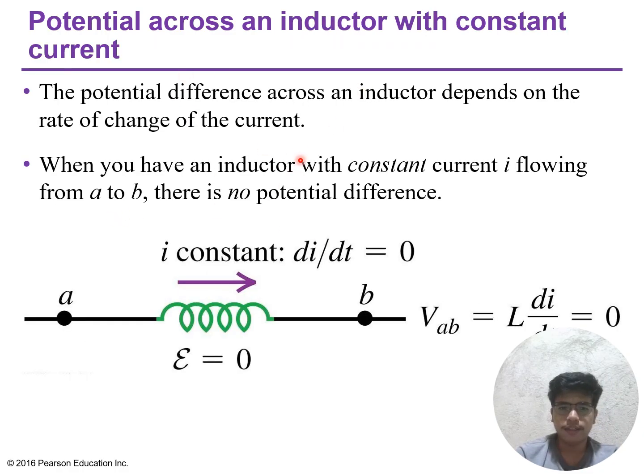When the current is constant, the voltage across an inductor is 0. So V subscript L is equal to L di over dt is equal to L times 0 is equal to 0. Unlike a resistor, where V subscript R is equal to IR. An inductor with steady current acts like a short circuit. In DC circuits at steady state, inductors can be replaced by shorts for analysis. At the moment a switch closes, t is equal to 0, the inductor opposes sudden current changes, acting like an open circuit, then gradually becomes a short as current stabilizes.